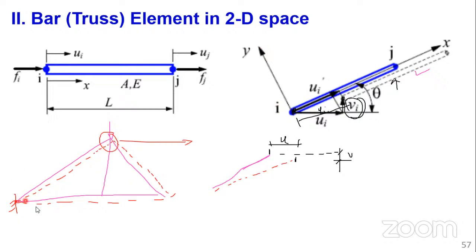But if we are considering globally, we are talking of a truss structure. In the truss structure, we can have vertical deformation and also horizontal deformation. As I have shown in this case, we can have vertical displacement and horizontal displacement for a truss at the global scale. So you could put it at the back of your mind that when we are talking of global, we are talking of the structure itself, the truss structure. When we are talking of local, we are talking of an individual element. For an individual element, because it carries axial load, there is no vertical deformation. It can only stretch or compress.